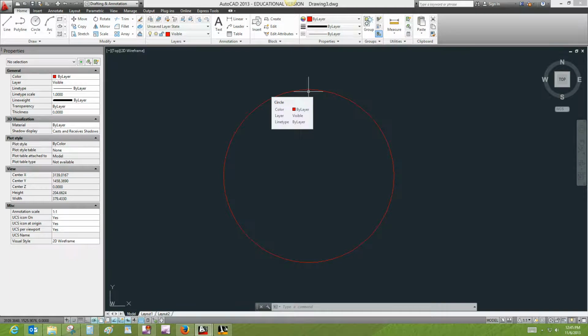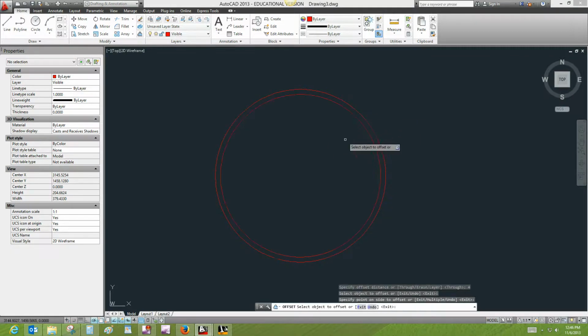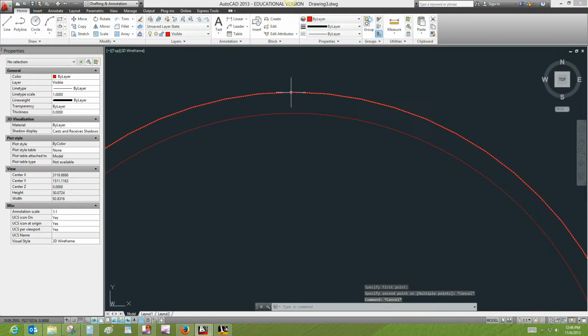So our other side, because it's a 45-degree chamfer, is also 4. If it were not a 45-degree, you wouldn't be able to say that. But let's just offset our front view by 4, and we may want to double check that before we submit, but the perpendicular distance from the outside circle to the inside circle is the distance of 4.